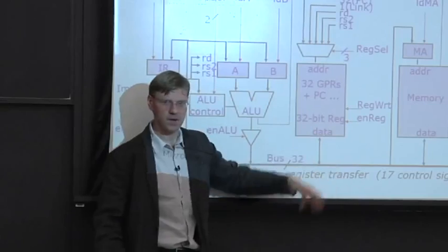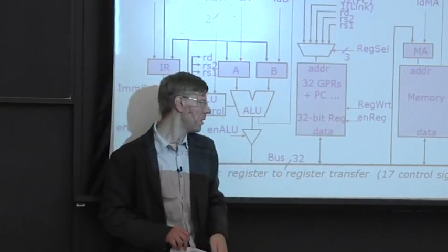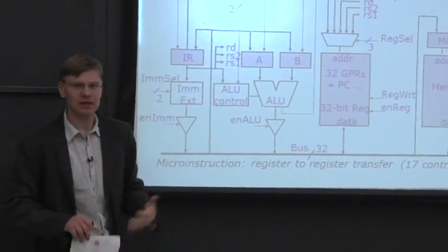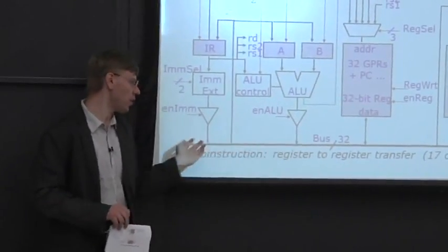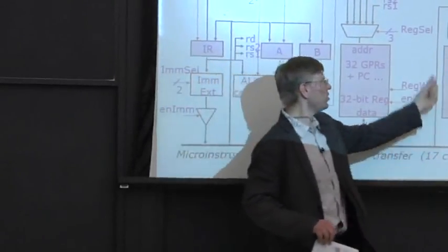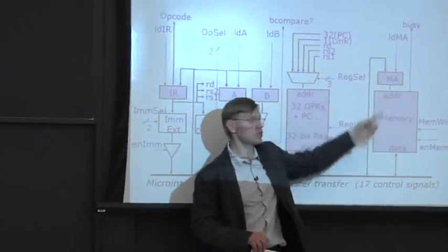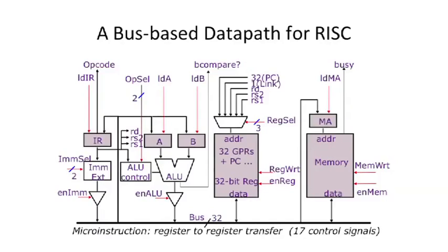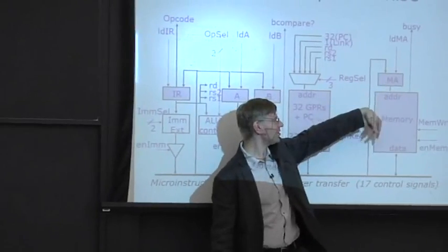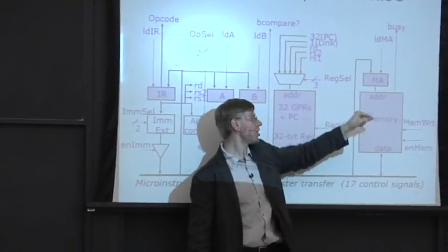The program counter is going to be asserted onto this bus, and now we need to latch it somewhere in a register. So it's going to be broadcast all the way on this bus, but we actually want to take it and load it into this memory address register here. And that'll finish our first cycle of our micro-coded control unit processor. The next cycle, this is all within one instruction,